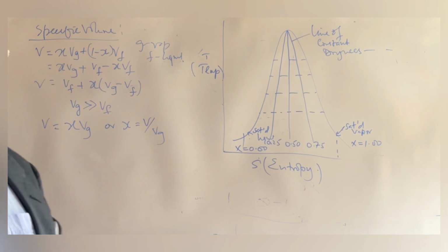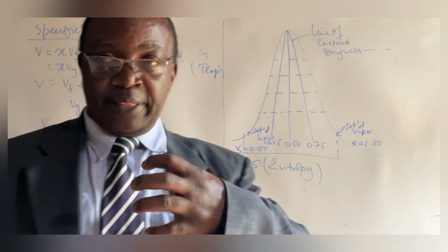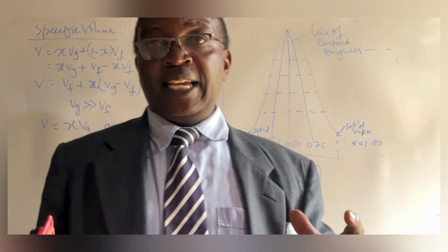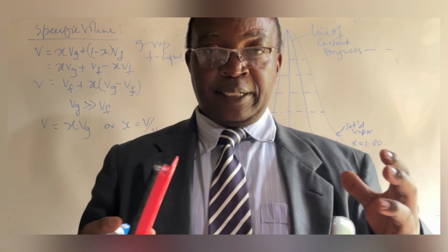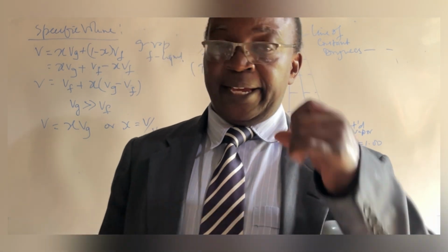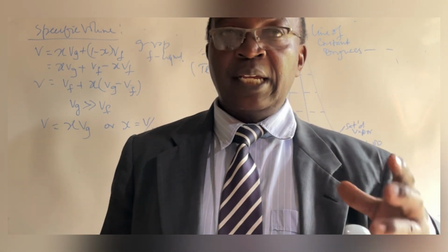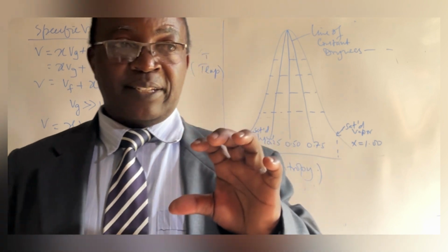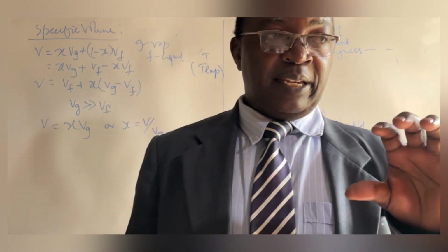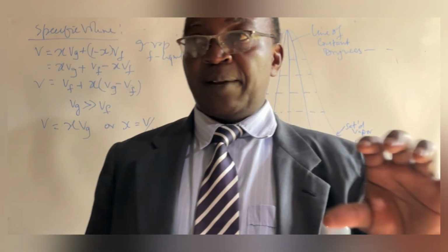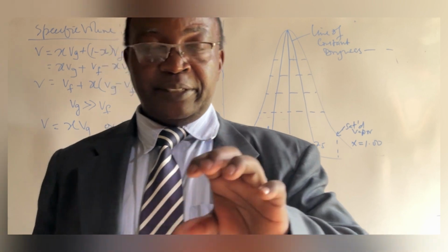In summary, very simple. The key question for handling the entropy-temperature diagram is the Clausius-Clapeyron equation, and realizing that heat transferred under constant pressure is the change in enthalpy, and heat transferred under constant volume is the change in internal energy.